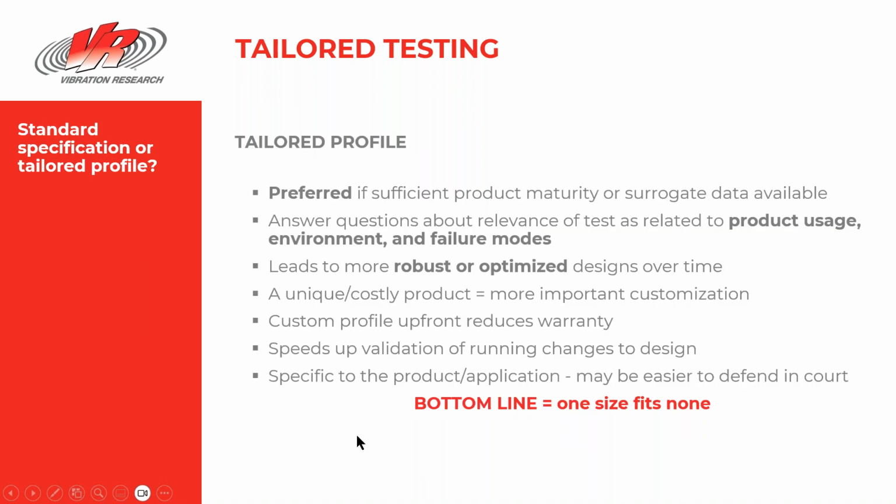So yeah, the bottom line really on test profiling is it can be preferred if sufficient product maturity or segregation in data is available. It answers questions about the relevance of tests in relation to product usage, environment, and failure modes. It can lead to more robust or optimized designs over time. Custom profiles reduce warranty costs and speed up validation, though there are running changes to design. So I'm a very strong advocate for tailored testing rather than standard specifications, but there are pluses and minuses associated.